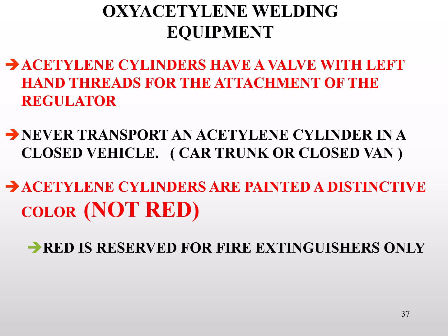Also, acetylene cylinders are painted a distinctive color, and black and orange are common colors. I have seen them other colors, but one thing is they'll never be red. Red is not used in cylinder gases because it is reserved for emergency fire equipment only. You would not want to accidentally open an acetylene valve to put a fire out. I assure you it would not work. So fire equipment is red, and cylinder gases will be painted other distinctive colors.